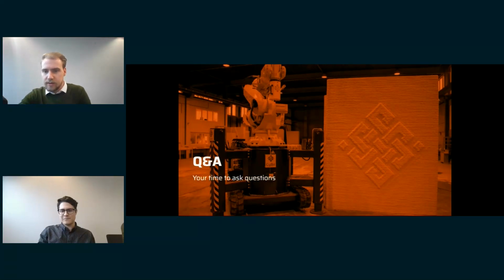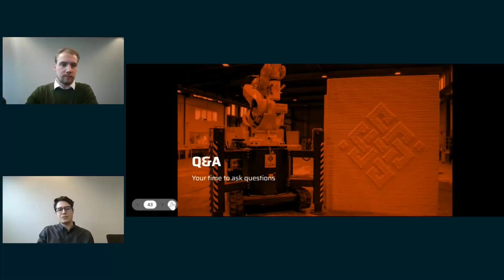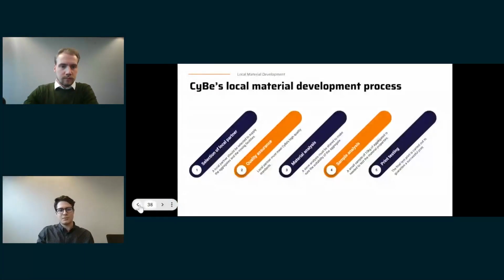Yes, Dinesh, indeed, 3DCP walls, in our case, act as lost formwork. After printing, you fill the middle portion with concrete. Well, not the entire wall, but we print, maybe you can go back to that slide. I believe it was slide 11, quite far back, so stick with us. This is also just for structural elements. If the element is not to be structural, we just don't do that.